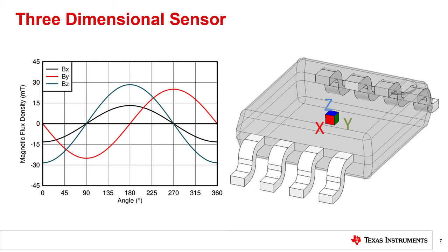than a one-dimensional sensor. If we revisit the plot from the real magnet shown before, we could now select the Z and Y components for this calculation. These two components are inherently 90 degrees out of phase throughout the entire magnet rotation. We now do not need to worry about alignment from channel to channel, and each Hall element in the same package will typically demonstrate better overall sensitivity matching than would be expected from two discrete sensors.